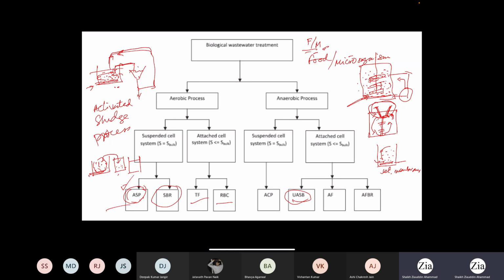In this case, it is a continuous system. Individual reactors are running in batch mode, but the overall process is continuous. You add certain things here and wait for the batch time. Then you put that content into the other reactor and wait for the batch time. Whenever the first batch is processed in the second reactor, another batch gets processed in the first reactor.